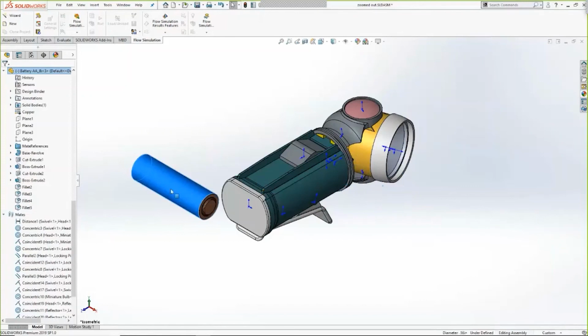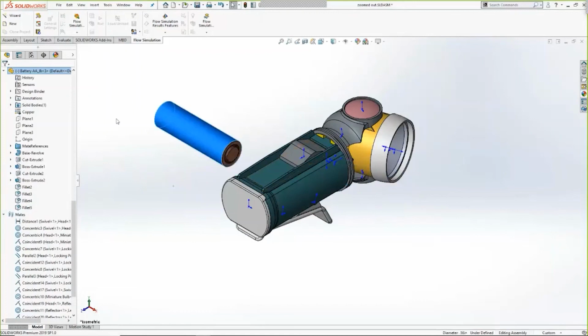So that's another reason your part could be missing. I did the F, it didn't work, the fit to screen. So I can find it here, and a really good hint on that is just turning on those origins so you can see the coordinate systems within the parts, because that'll kind of give away what's happening there. All right, I'm going to close that out.